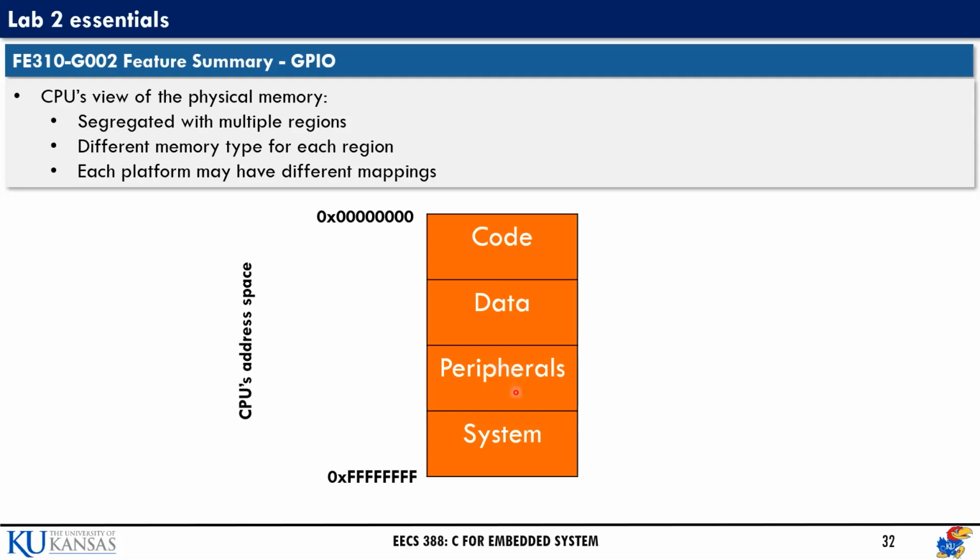And last but not least, if we need dynamic memory allocation, we don't know the exact size of our data, and if our memory is unified, not divided into different segments, we might accidentally overwrite a region of the code. So that's very dangerous, right?